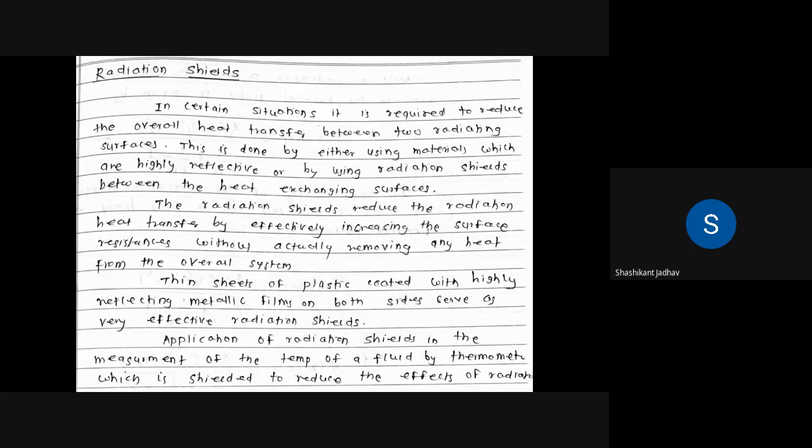Okay. So in the last point we covered that there are two plates and each plate is emitting radiation to the other plate. For that we considered the surface resistance and space resistance, and by using that equation we calculated the net heat transfer. So between the two plates, energy exchange takes place, and for that we have written the equation.